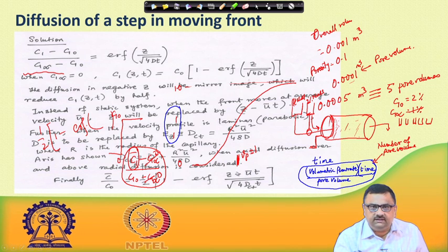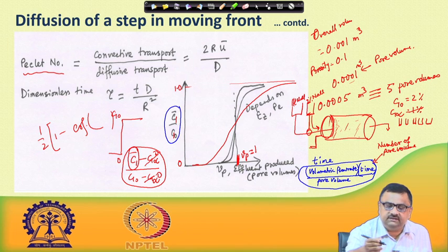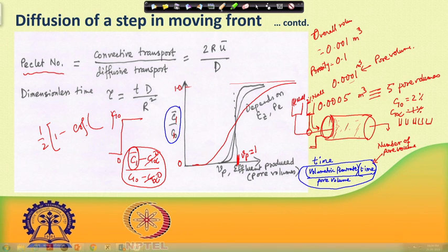These are experimental measurements, and we know what velocity this fluid is being injected at, and at the outlet at a given time what the concentrations are. So, since the only unknown is this dCT, one can find out what is the dCT that corresponds to this particular profile.